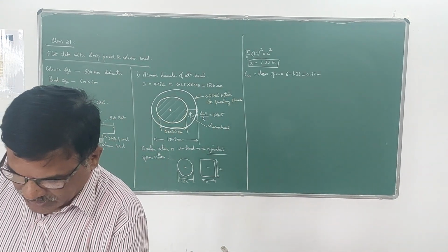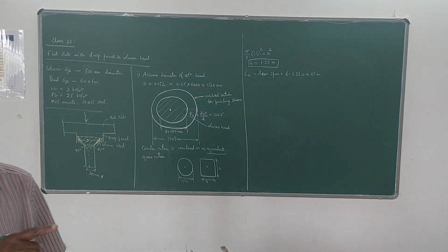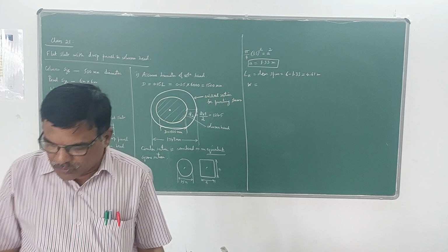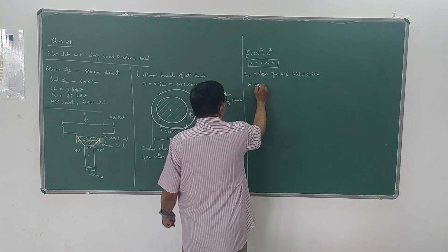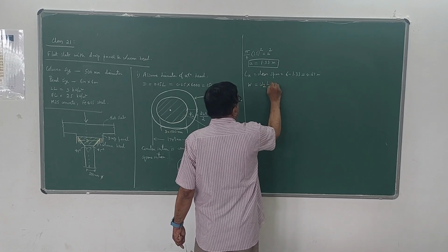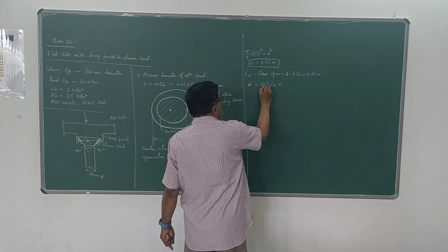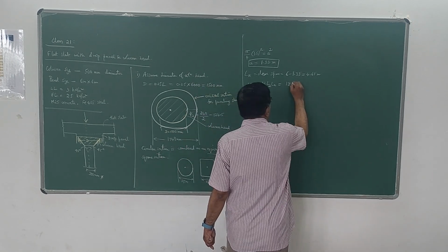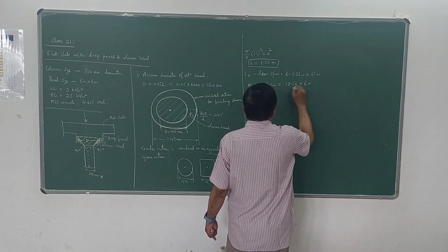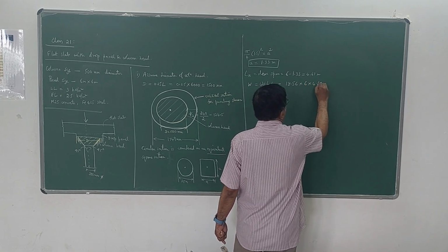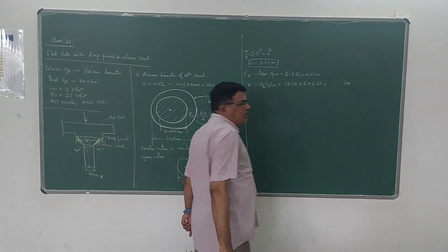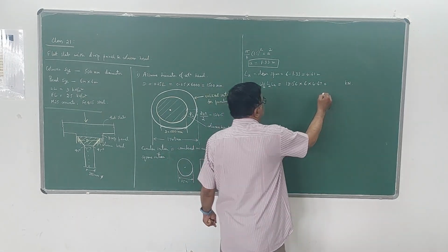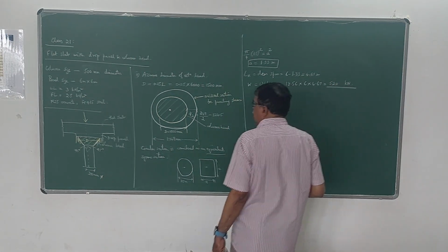Then we have to calculate the load coming on that panel, or the column head, capital W. This capital W is nothing but Wu into L2 into Ln, the same formula we used in the last lecture. Wu, from the last problem, is 18.56, the ultimate load. L2 is 6 meters, Ln is 4.67. This gives the equivalent concentrated load acting on the column head, 520 kilonewton. So this is step 1.